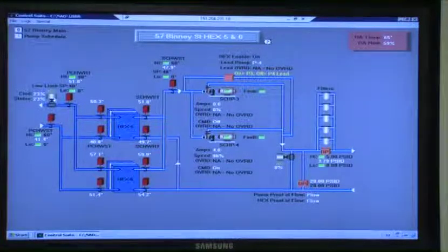It's 23% open, that's what's controlling that to open and close and maintain the temperature set point. So this here is controlling that valve to open and close to get to our 48. Everything else is informational only, for temperature anyway.